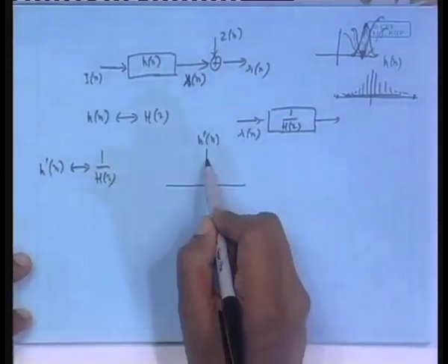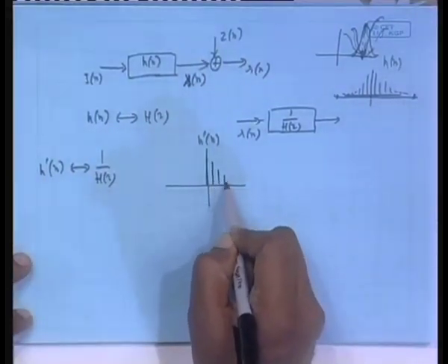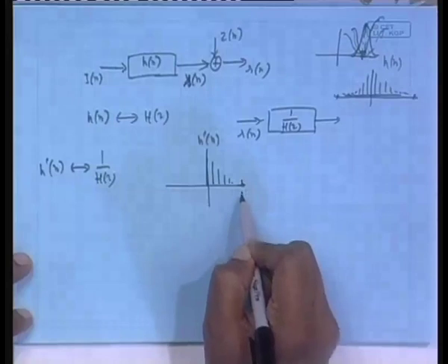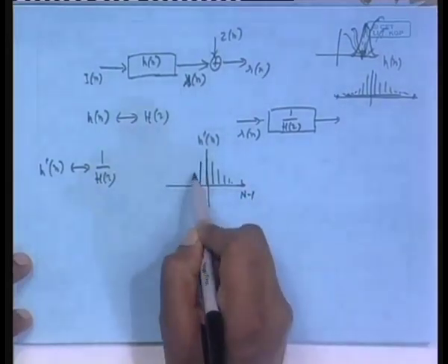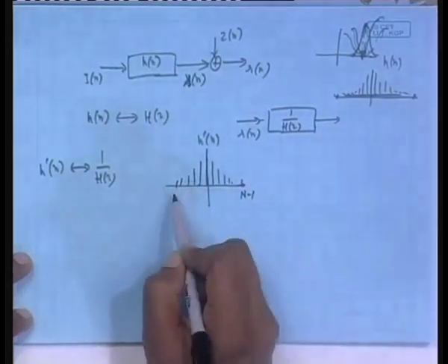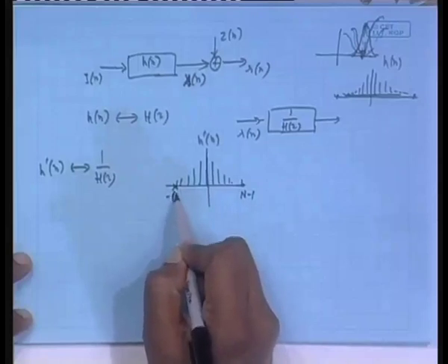In fact, in the analog case, if you deal with RC circuit, RL circuit, you see all those e to the power minus t by RC, e to the power minus t by L, all those are dying. Those are basically impulse responses. They have to die out so that they are absolutely summable. So, that means this will die out. You can truncate it up to some point n minus 1, and on this side also, it is not necessarily symmetric on both sides, up to this.